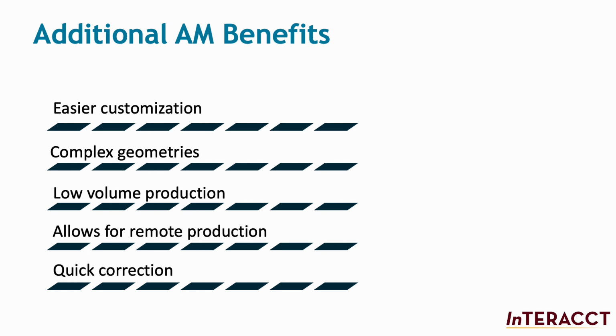In addition, the manufacturing methods themselves allow for easier customization and production of complex geometries. Unlike conventional manufacturing, such as casting or molding, in which equipment and equipment parts must be pre-manufactured, acquired, and installed in the machine before parts can be produced, the computer-driven digital design and layer-by-layer method of additive manufacturing is more nimble and flexible in what is produced. With additive manufacturing, the low cost of setup makes low-volume production economically feasible. If problems are found with a prototype, corrections can be made quickly and a new prototype produced.